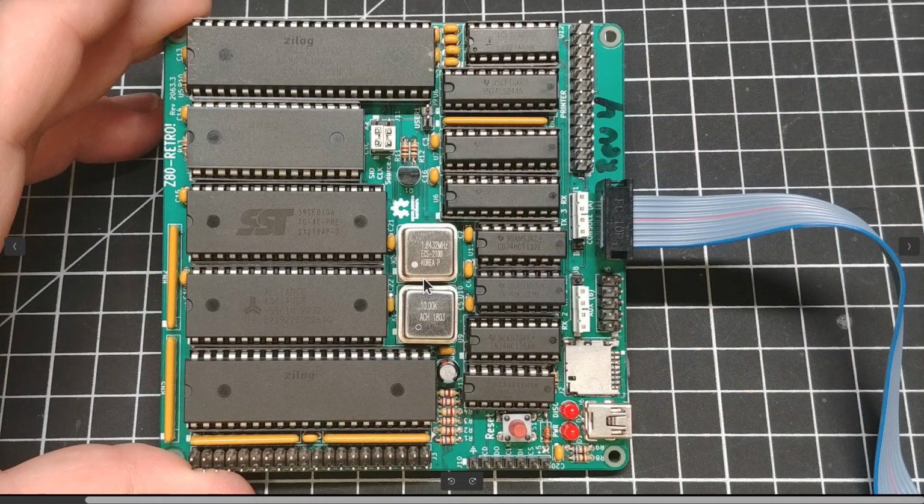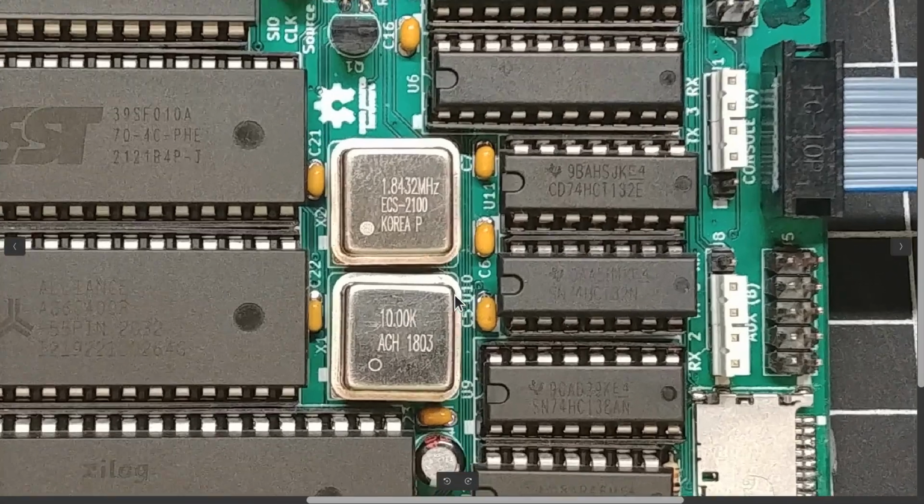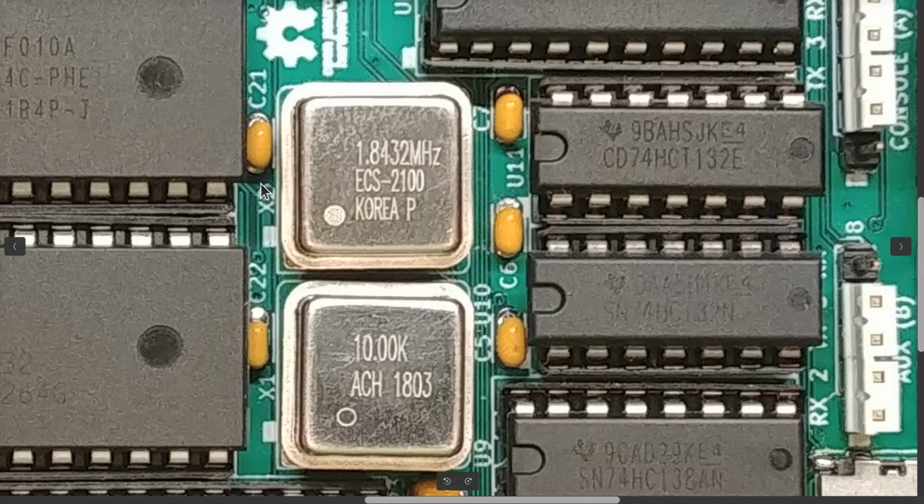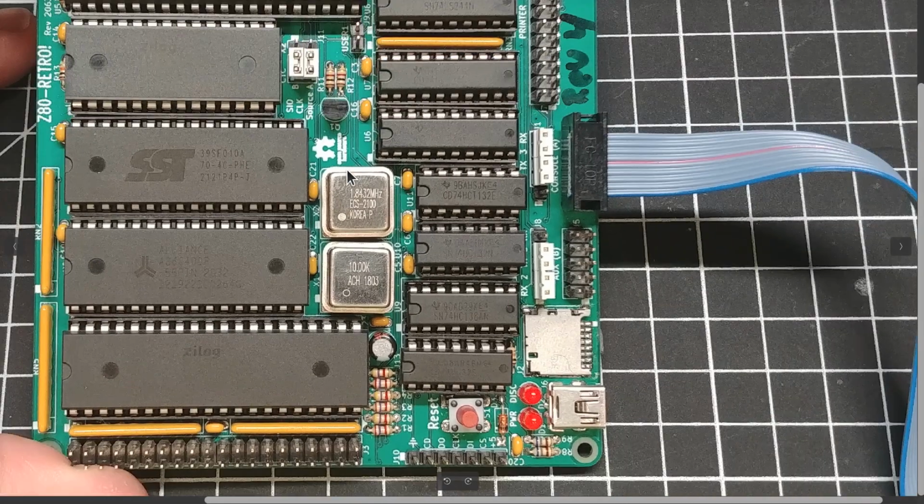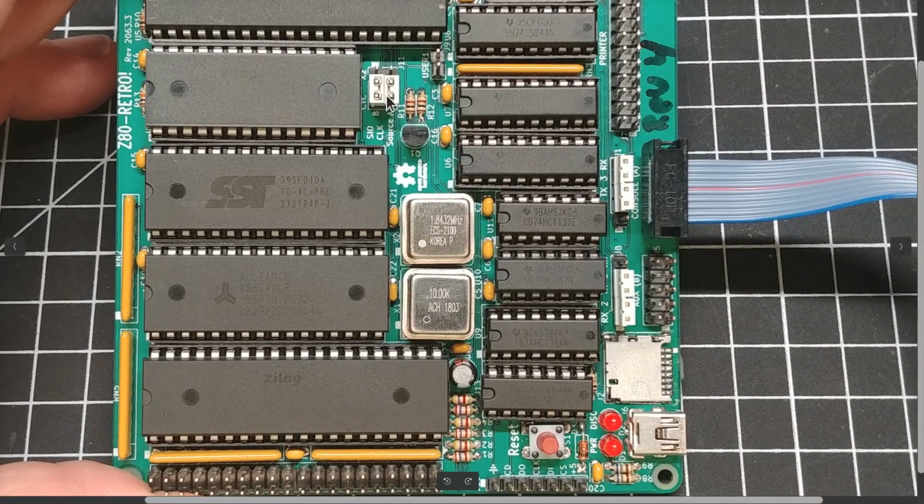Now, to that end, let's make sure that we all understand exactly how I've configured my retro board. All right, here's a picture of mine. Arguably, maybe perhaps this is sideways, but for some reason I was trying to get rid of the glare on these two oscillator cans. So let's look very closely at how I've jumpered this board and what oscillators are running at what speed. If we zoom in really close, this here is X2, and it's running at 1.8432 megahertz, right? This is only used to go into the CTC over here and this header here that has to be jumpered correctly. We'll get there in a minute.